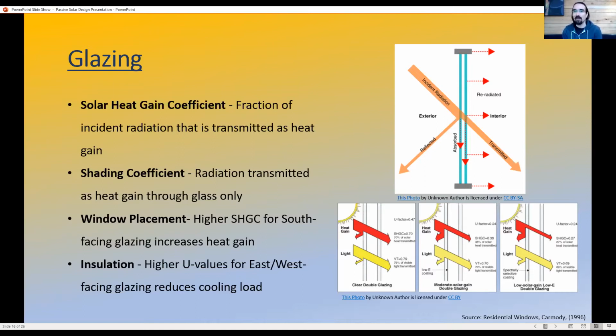And if you have one whole wall of your house that has only an R4, you're going to have a lot of heat transfer through that wall at times when you don't have the solar collection happening. So at night, when there's no sun coming through, you'd be losing a lot of heat through that. And in areas where you're going to have a lot of cooling loads, you could be transferring a lot more heat into the house during the summer than you would like.